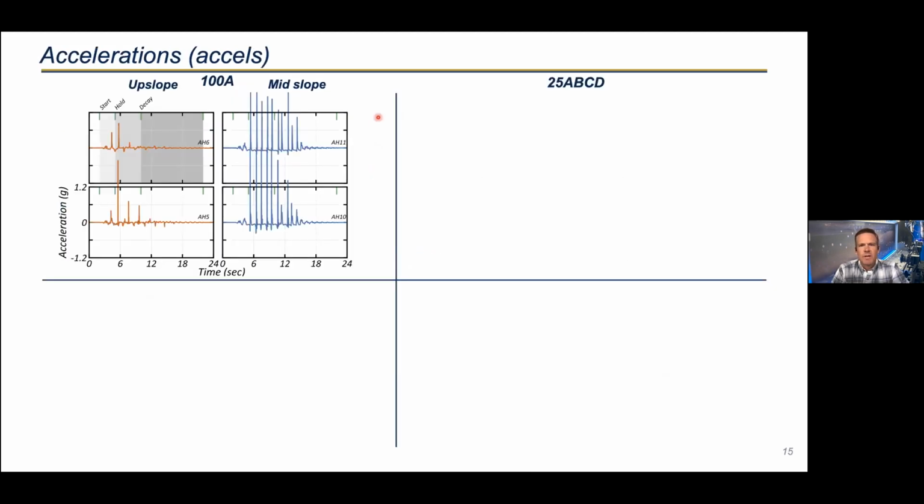So we're going to first begin in just the upper left. This is the poorly graded soil, and we're going to begin with this one because this is our benchmark knowledge. You can see, first of all, that the accelerations die away within the first 2 cycles. This is the classic exhibition of a fully liquefied case in the upper accelerometer, and even in the second level, it's also essentially liquefied throughout the shaking process. That's on the level ground condition. On the upslope condition, there are some indications that we have some dilation spikes.